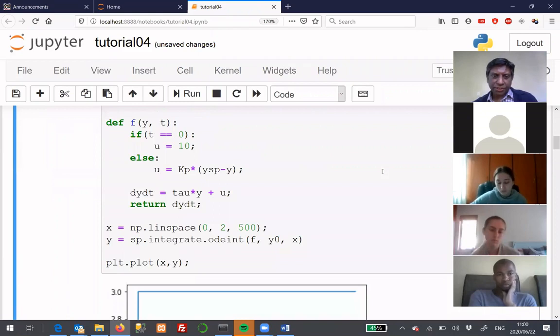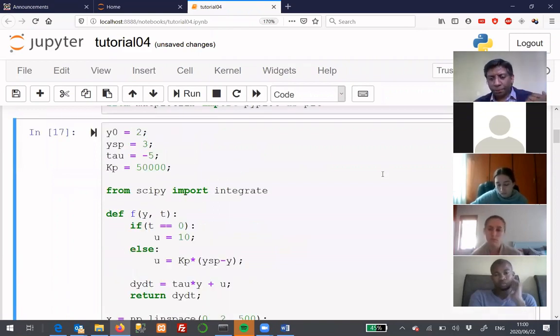So just saying that we implement control doesn't automatically mean that we are going to reach that steady state value, right? It doesn't automatically mean we are going to reach the intended set point. So implementing control means that we do have to tune that controller as well. So the constant behind that controller, that Kp value, we have to find values of Kp that accomplish the intended goal, right?